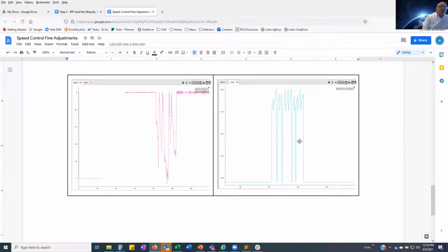Yeah, remember I have two mechanisms for measuring speed. One is the GPS. I've got an RTK signal and it's putting out a speed value based on the movement of the GPS position. Have you plotted that? Ideally plot that at the same time you're plotting this pink graph here, so you've got values coming off the wheels and values coming off the GPS. Do those look the same when you do that?